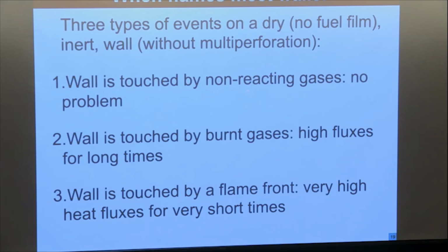The first thing is that if the wall is far away from the flame and is only feeling fresh gases, there's no problem. Then the wall also can be in the burnt gases, and then you have a problem of heat transfer. And the worst situation is that the wall is at a place where a flame comes from time to time and hits the wall. That's the highest flux there, and that's the situation we want to avoid.